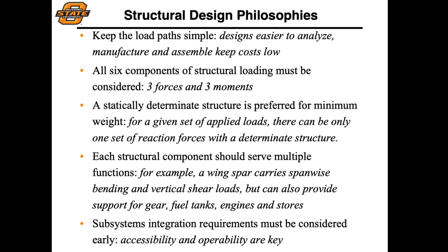You have to make sure that you're analyzing all 6 components of the structural loads acting on your aircraft. So you have to consider not only the forces, which is what we've primarily focused on so far, but also the moments acting on your aircraft. How is the wing not only being bent along the span, but also being twisted by the aerodynamic moment acting on it, for example.